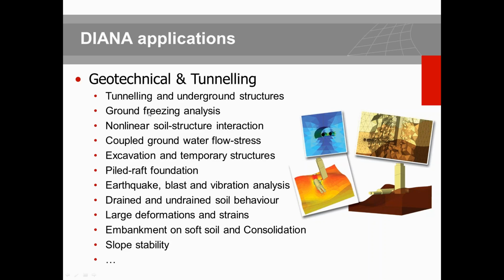Ground freezing, nonlinear soil structure interaction. So besides conventional nonlinear springs, in DIANA we offer nonlinear constitutive models associated to the interface elements, and you can consider these types of elements and behavior to simulate the real nonlinear effect on the structure and the soil. Fully coupled groundwater flow covers the effect of seepage and the deformation and failure of structures.